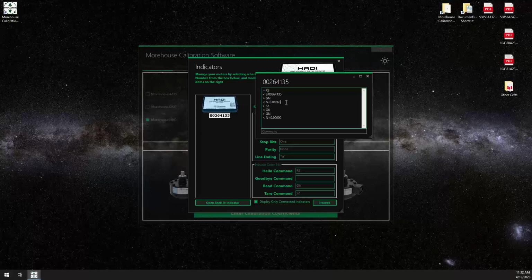But yeah, for those, that's considerable, depending. And you're not too far off, because on a 2 millivolt load cell that would be 5%, and on a 4 millivolt load cell it's 2.5%. So it depends on the output of the load cell. But if you just go with 0.1, and it's not zeroing, chances are there's a significant shift or overload on the load cell. Again, careful wording, I said chances are.